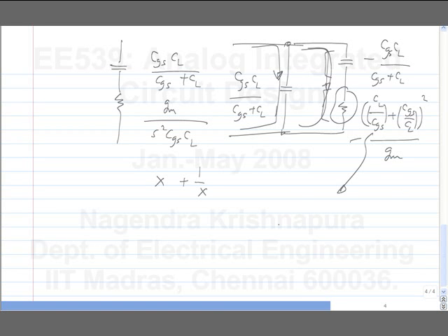And I had also mentioned earlier that you can use this as an oscillator instead of an amplifier, in which case you explicitly connect a capacitance here. The ratio is not always 1, but something close to 1, 2 or 3 or something of the sort. Okay. So you have to do this because in an oscillator, the negative resistance is what you want. When you want to use it as an amplifier, negative resistance is a nuisance. Whereas when you want an oscillator, that's what you want.